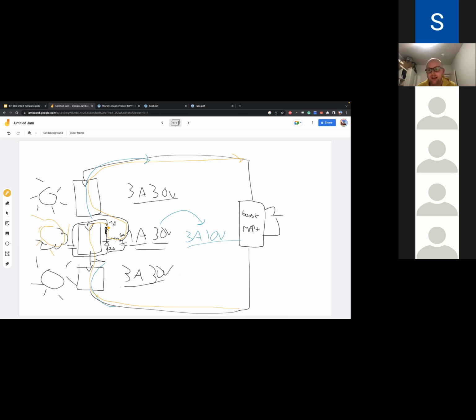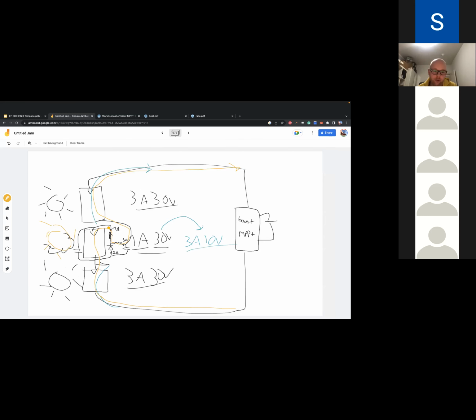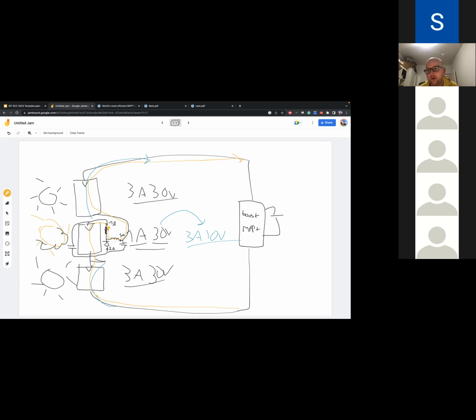Attaching voltage measurements to your array, to see when diodes go into conduction and what the voltages are on your cells and how much lower they are than you would ideally hope, is the first step towards optimizing your system, right?